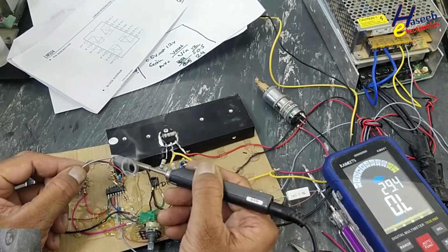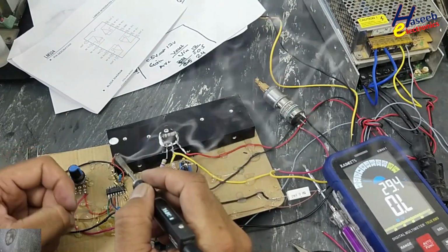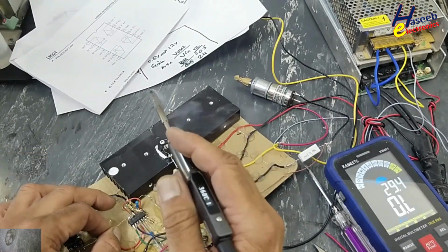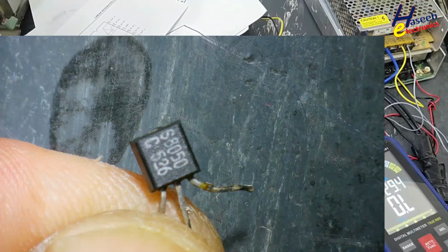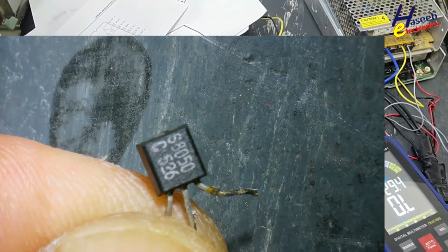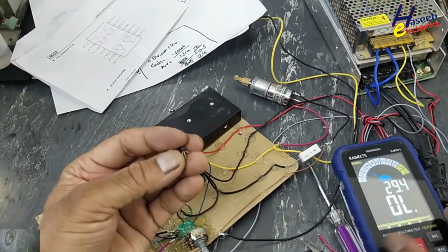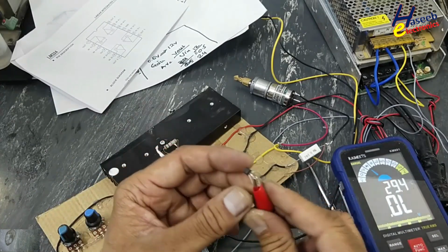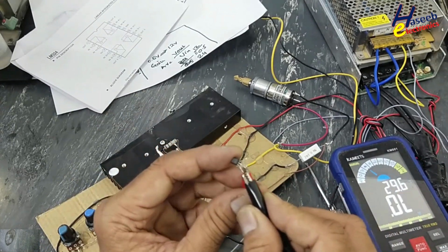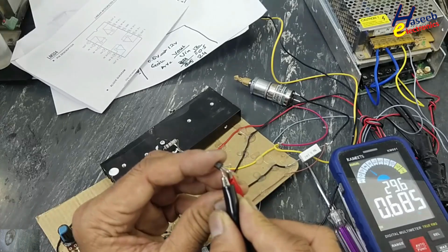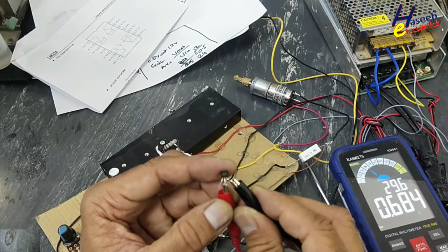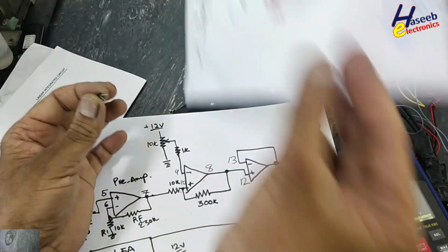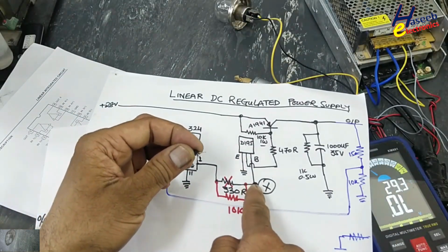You can also create a PCB using this diagram. I will jumper pin number 13 and 14 together to connect this output resistor. I will use an S8050 NPN transistor, center pin base, left side emitter. Collector of this transistor will reach the base of this transistor.